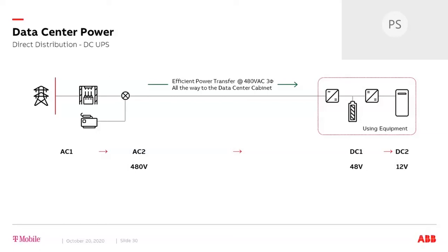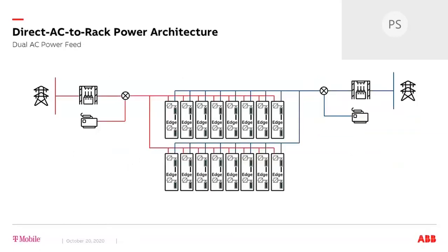While this DC powertrain is nice and efficient, Don, you also wanted to increase the reliability of power to your revenue-generating equipment by a significant amount, didn't you? That's right. This AC power input scheme improves supply power reliability so much, an extended runtime battery system is no longer valuable. The battery capacity needed is reduced to only the bridge time for utility to generator transitions. We reduced battery energy storage by 85 to 97%.